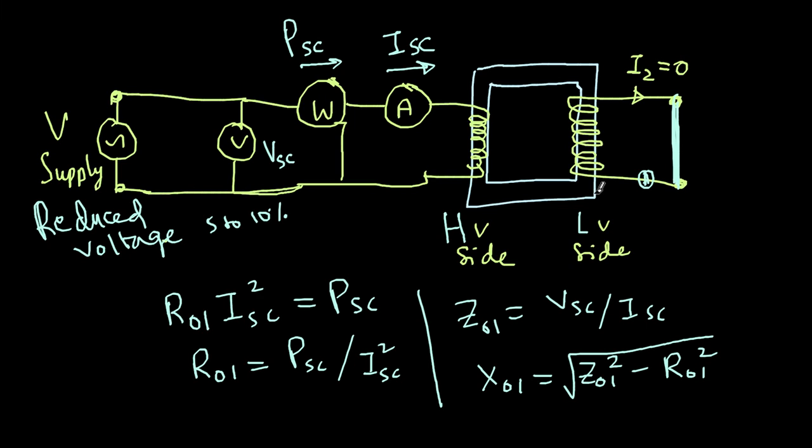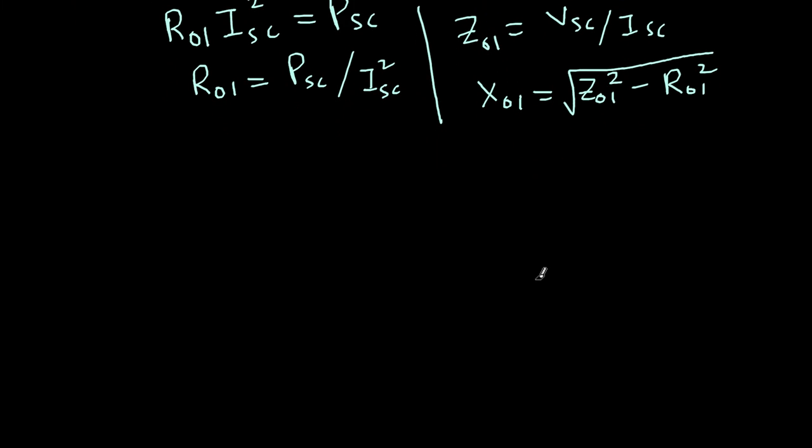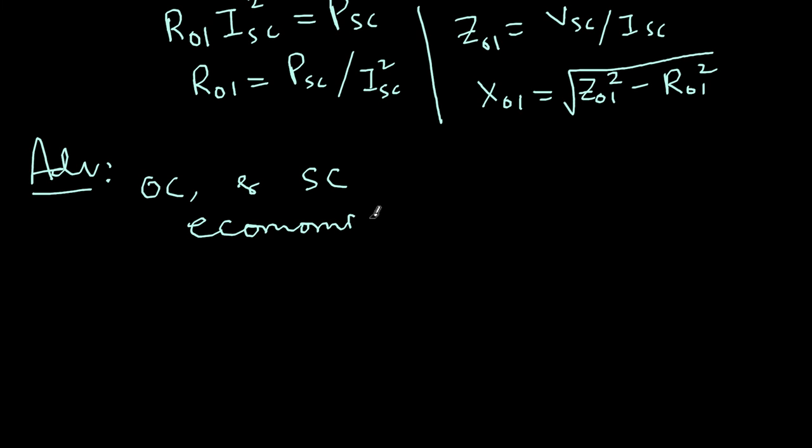So what are the advantages of this open circuit and short circuit test? First, both the OC and SC tests are economical to do, because at any time these are operating on no load. Open circuit has no load, and short circuit also needs no load.